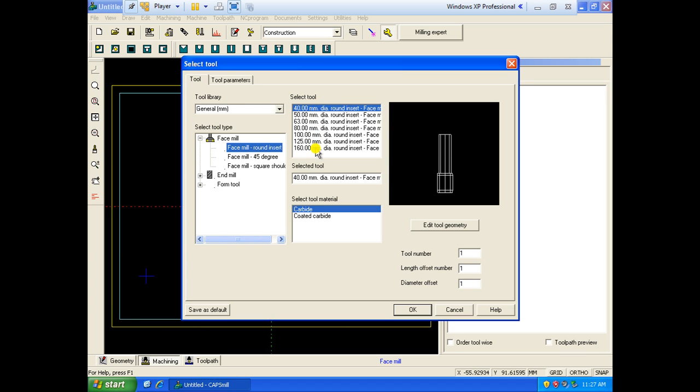If you choose the maximum with the minimum, it should be available in the industry, as well as it requires only minimum time to remove the material. So medium, even though not a small diameter, nor the maximum diameter, let me consider a medium-sized tool, that is a 100 mm diameter.